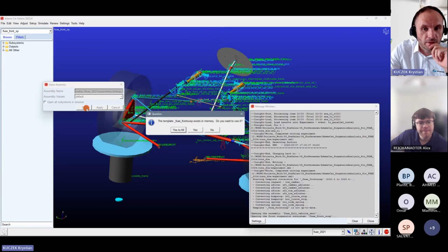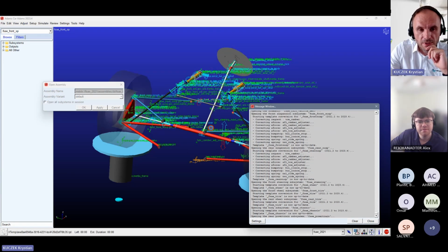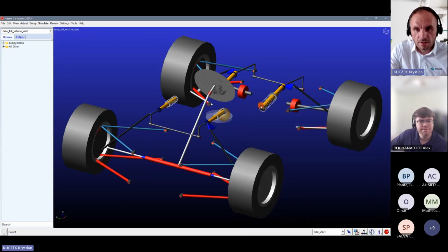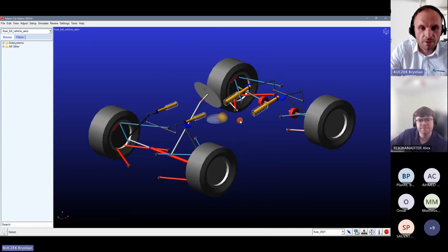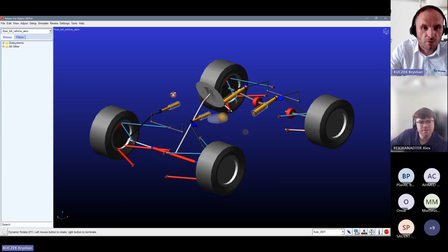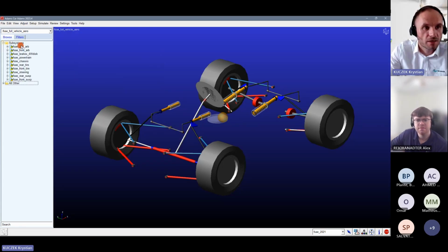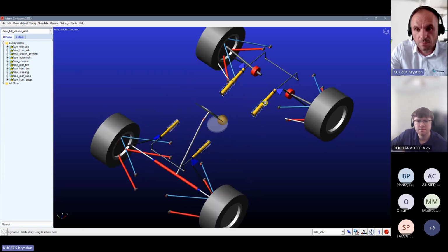Let me just open it from scratch. As I said, go to the Sim Companion website and look for the link to the FSAE database in Adams Car. By using that, you will be able to get the database with the running model, our full vehicle assembly, where you have the chassis part, the tires, the steering, and the rear axle with the drive shafts.